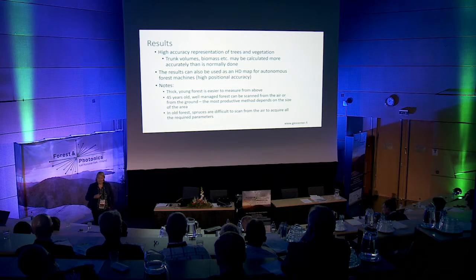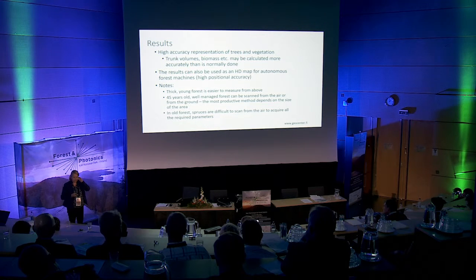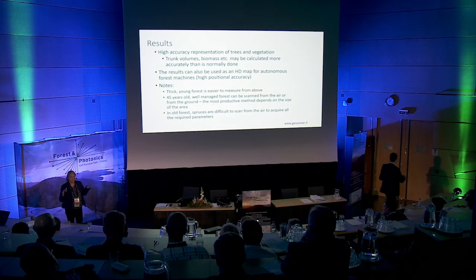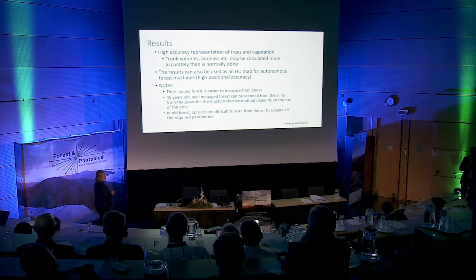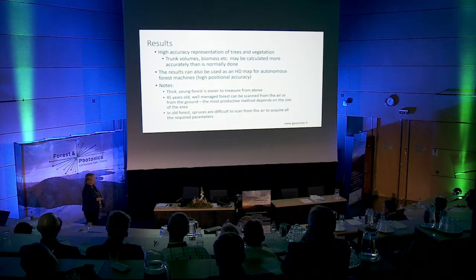And as for the forests, I'm sure that you're more interested in the forest part here. The young forest that was really thick with the under vegetation, it was very difficult for a human to go there and actually scan. Yeah, you could do that, but the next question is, how do I get my scan positions together? So really, I think UAV or something acquired from the air is a much better solution for those. The 45-year-old forest, that was like either or. Also in question of time, because we only had a few hectares to scan.